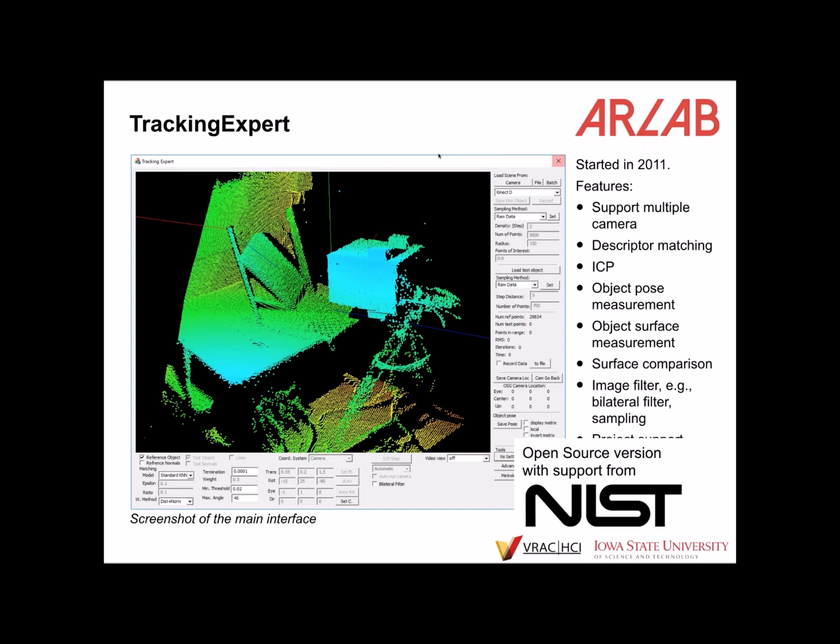So one question is, in addition to the Kalman filtering, do you currently use any predictive feed forward for real-time motion tracking? So predictive algorithms to estimate the future position. Yeah, we have a Gaussian model, based on Gaussian mixture. We don't use this for real-time pose estimation, but we use this to analyze a sequence of images, and then to predict. The Kalman filter also predicts the current pose, but not the future.